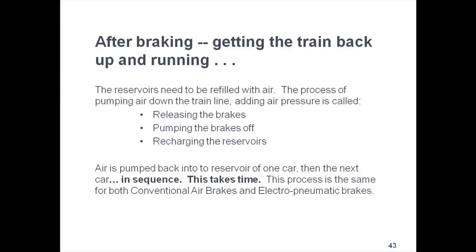Ideally, however, a running release can be accomplished. This means the train might slow down from 60 to 40 or even to 20 while air is being pumped back into the reservoirs, but the train doesn't stop. It avoids the stop, which is good.